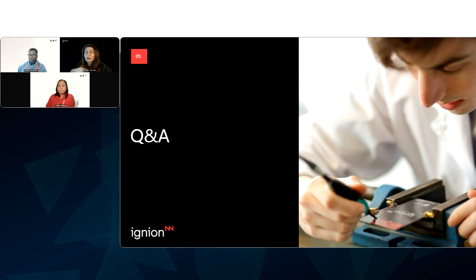For example, using some LTS technology or something like that. Or use some flex antenna that can go up over your PCB, and still have the size of the PCB as a ground plane. So we usually try to think outside of the box. We try to maybe integrate some surrounding space for antenna. For example, in smartwatches, I worked on one project where we used a metal element, like a ring around the screen, as an antenna.